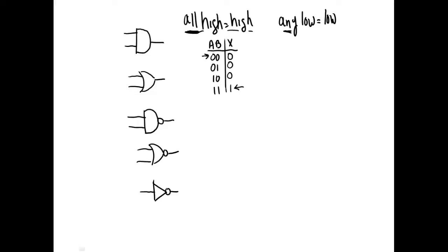You okay, Morris? Okay, so let's draw this symbol. Anytime I say any, I'm going to draw this, right? I'm going to come up here and I'm going to draw this. Y'all follow me so far? Okay. Then I'm going to come over here and I'm going to look at the inputs, and the inputs are low active, and I'm going to put a bubble on the output.